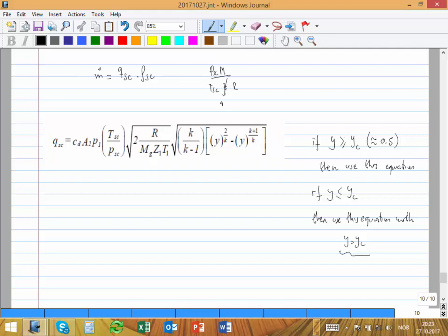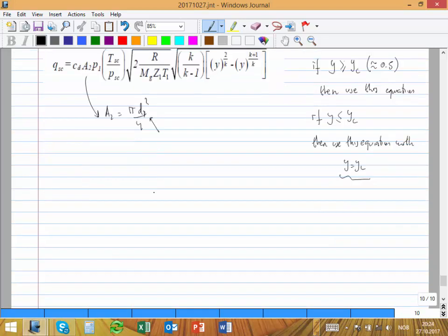So that's the equation we're going to use, and let's see if we can do an exercise to wake you up and see how much you got. There is something interesting: this area 2 is pi times the diameter squared over 4, and this is the diameter of the throat of the choke, basically the diameter of the bean choke that I have to use. So that's just to show you the equation and where it came from.